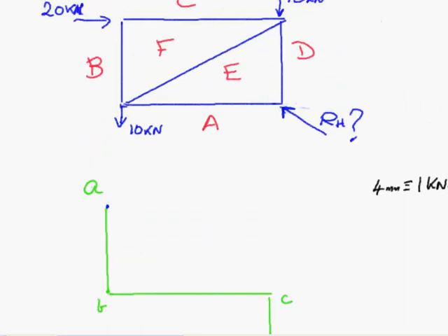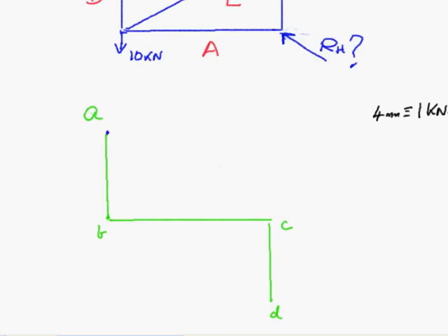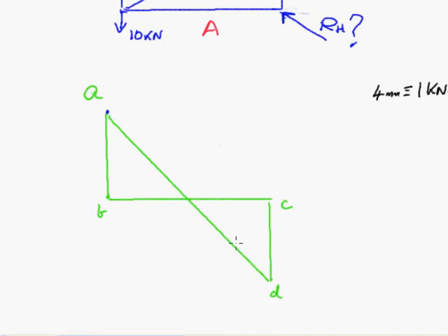And you can see on here that we've already got DA representing our hinge, our unknown force. We've got it on here, d to a, so it's a line up there joining d to a. The direction of that reaction force at the hinge is from d to a. So it's in the direction that we actually drew it.